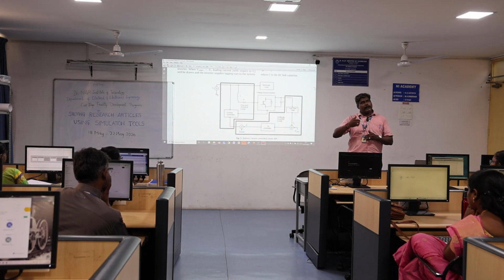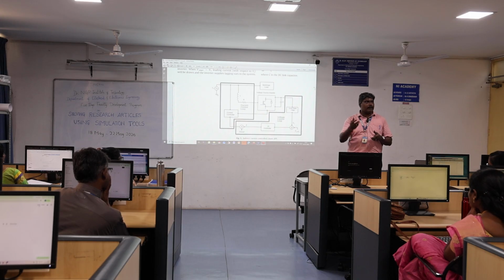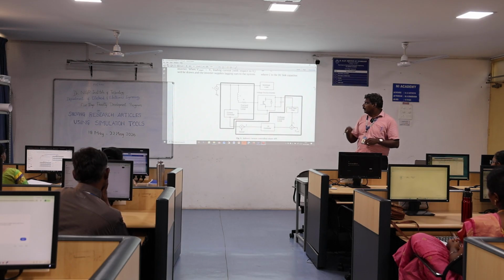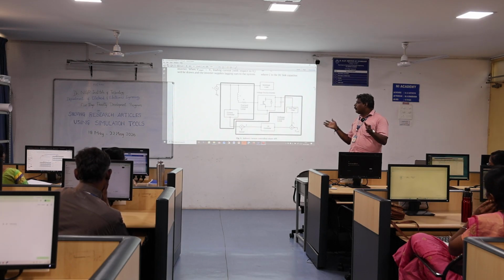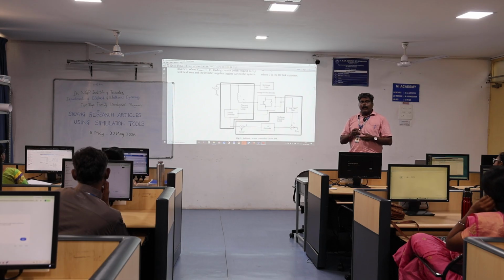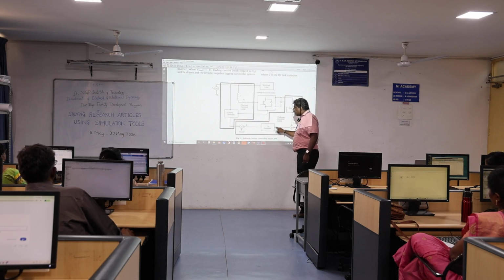Right? When you go for the integral controller, it is the reverse. We have a minimum steady state error, that is called ESS, steady state error. Mathematically, we represent it as ESS. Then poor transient response. So whatever the drawback in the proportional controller and benefits, similarly whatever the drawback in the I controller, integral controller and benefits, if we combine them together, then we can go for a PI controller to reduce the steady state error and also to improve the transient response. So that's why we go for the proportional integral controllers.